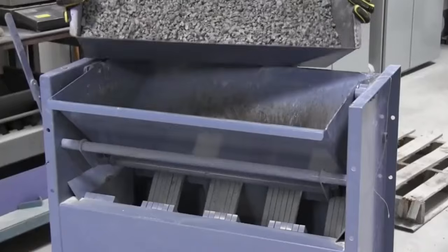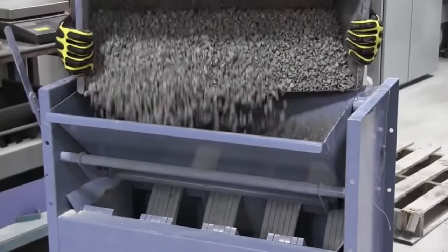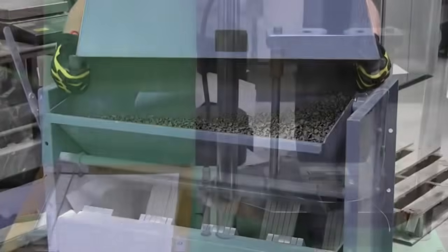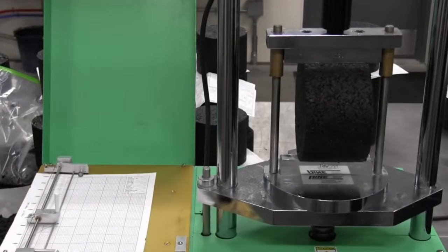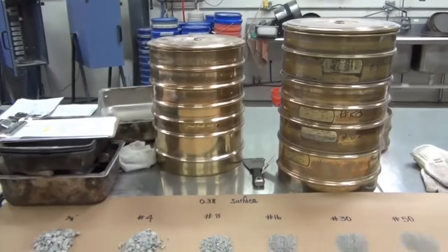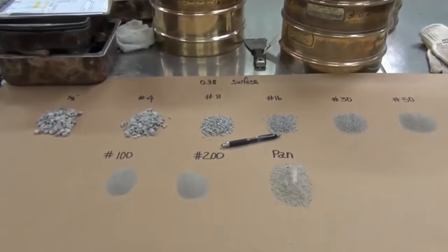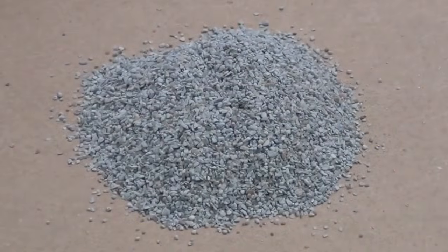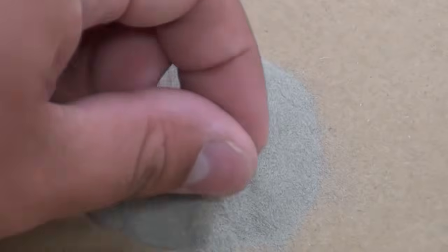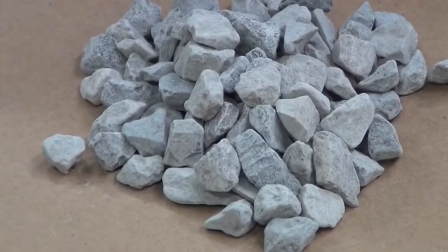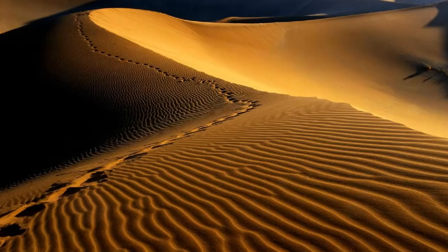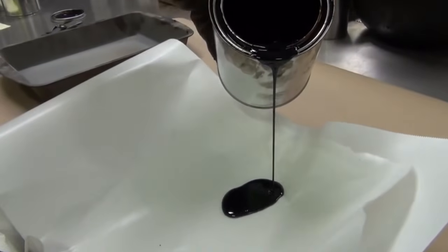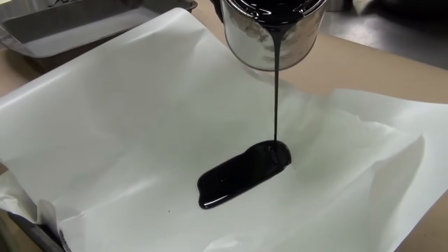The coarse aggregate shall be the blend of crushed aggregates from 6 mm to 25 mm, and it shall be cubical or angular in shape, and it shall satisfy all other specifications. Fine aggregates shall be passing the 2.36 mm sieve and retained on the 75 micron sieve, consisting of crusher run screening. The important thing to know is that natural sand is not allowed as a fine aggregate in any of the asphalt work. Generally, the 80 to 100 grade bitumen is used as binder content in highways.